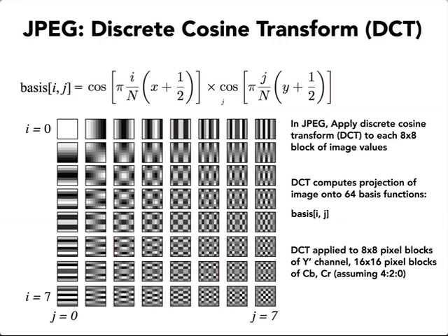It's also 2D basis functions because we're using it for image compression, both in the i horizontal direction and j vertical direction. These are the basis functions for an 8x8 block of pixels. If we put it into a discrete cosine transform, then these would be the 64 basis functions for representing an 8x8 block of image values in DCT coefficients. What does this mean? It just means that we take a block of 8x8 pixels and we represent it by a linearly weighted combination of these basis functions.